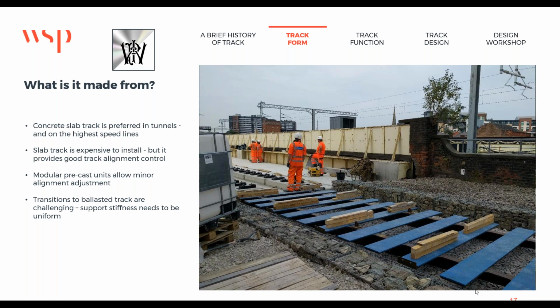Oh, the tamper's fallen off again. Okay, that kind of thing. Or if you're in a pendulum and you derail on a twist fault, you'll have people and body bags and all sorts of mess to clean up. So the twist fault will create the derailment. The speed will create the aftermath.